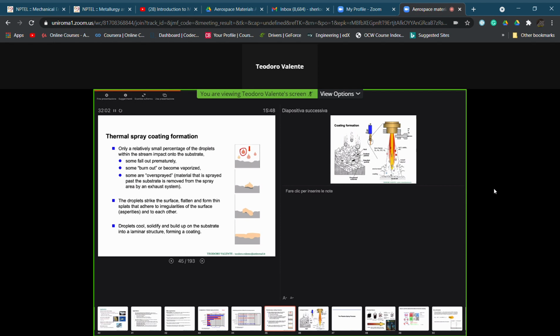If we go on to overheating because we have melting, then we can start a vaporization process of the powder itself. So we do have an upper limit, let me say, for what concerns the particle average diameter due to the necessity to melt the powders. We also have a lower limit, which we need to overcome in order to minimize the vaporization after melting.